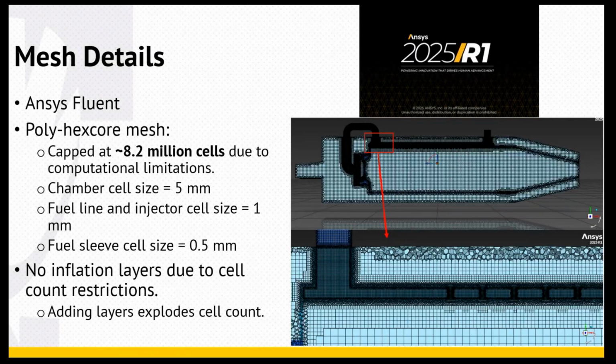So I had to make some compromises on my mesh resolution in places that count, particularly in the flame zone. But because the most important aspect for me is the cracking region, I try to refine that down as much as I can.